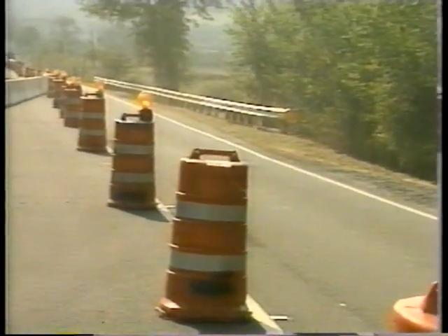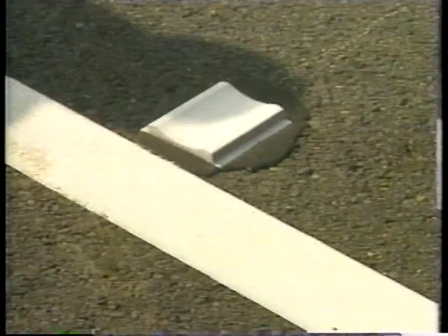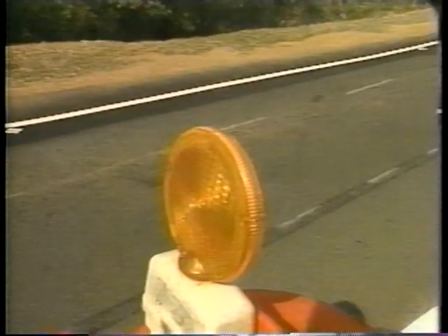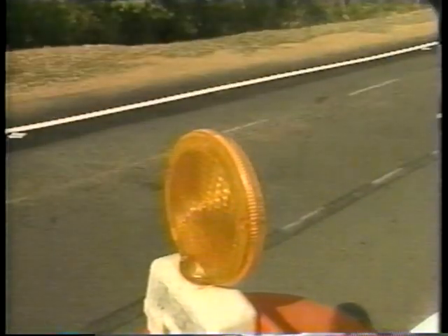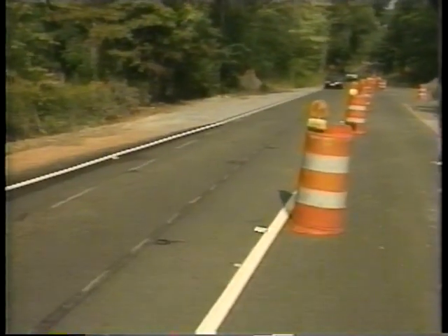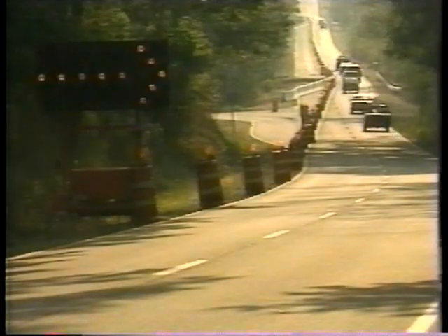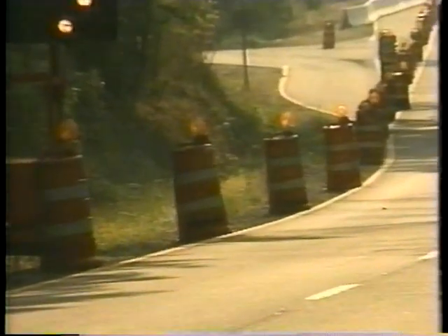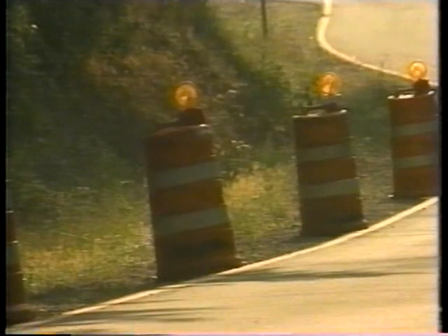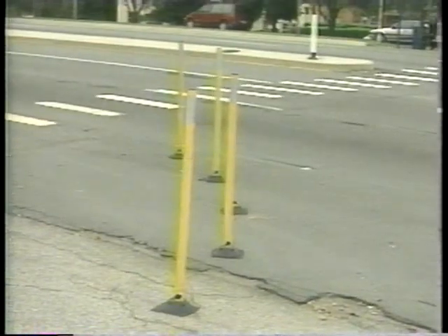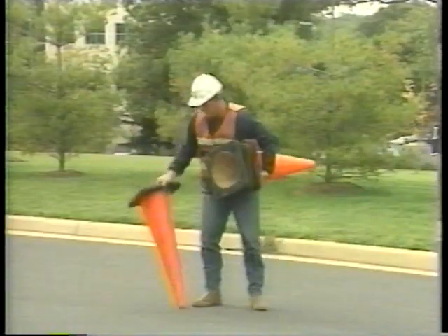Markings outline the vehicular path leading traffic safely around a work area. There are pavement markings used by drivers as a primary means of guidance, and delineators or lights used to supplement other devices by further defining a safe path. Devices specific to work zones include channelizing devices that warn traffic away from or around a work area. There are drums, tubular markers, and cones.